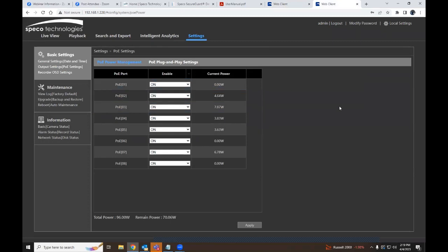If we're trying to do service on an account and we got a call that came in and said, hey, this camera's locking up, it's not running the analytics, or this camera's not switching to infrared, with network cameras, whether it's a flashlight, something can happen. It happens to everybody's cameras. I'm not going to say it doesn't happen to ours, because everybody would know that network issues happen. And network issues can usually be fixed by a quick power cycle.